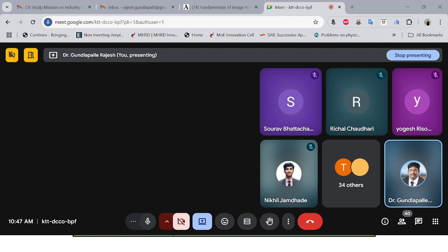If it is a store, it stores the multiple words to the memory location given by RD, and then increments after each and every transfer. So this LDM and STM are thumb instructions. With the thumb instructions, if you want to transfer 32 bits, then you have to use the extension called .w. If you are not using .w, only the half word will be transferred.